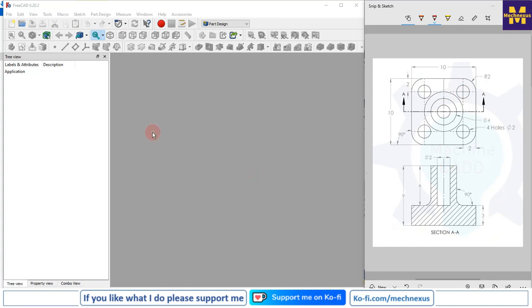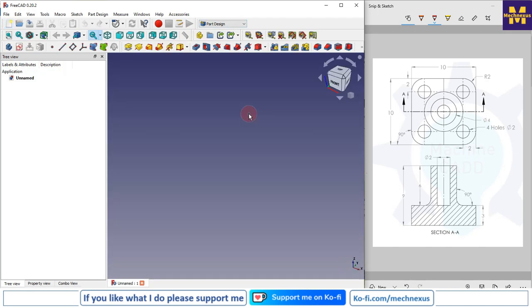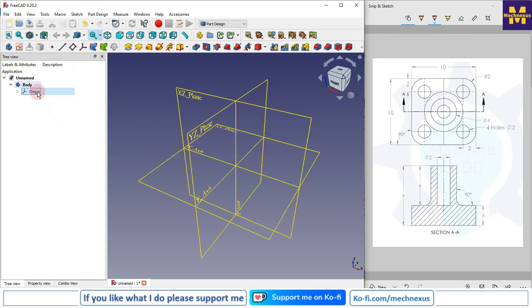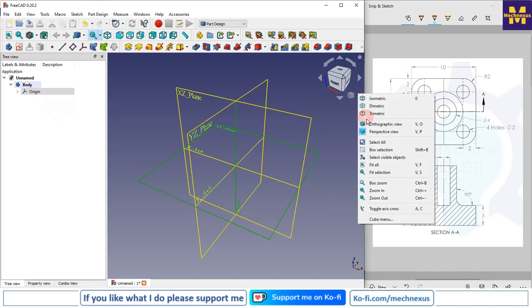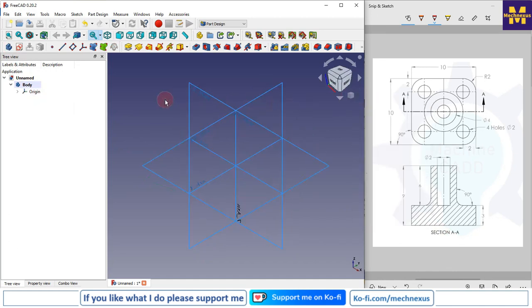In this tutorial we will learn how to convert this orthographic drawing into the 3D model. For this we will activate the Part Design workbench, which is activated here. Now we will create a new file, and here we will create a body. I will turn on my plane, and from here I will switch to the orthographic, then isometric.